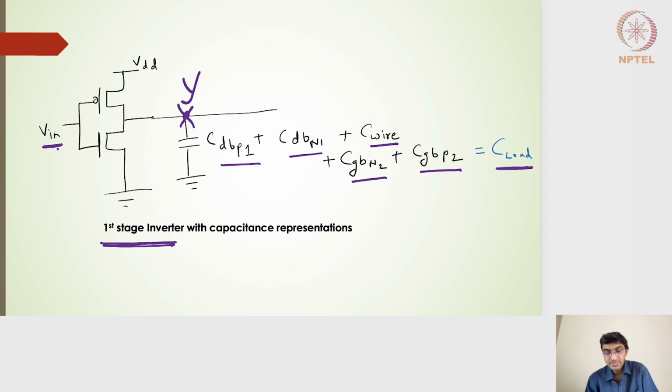So what we had seen was a completely different module on delay. We understood the definition of the propagation delay and the contamination delay, falling and then rising, and then we started looking at the inverter circuit, understood all the capacitances, the input capacitances, and the parasitic or depletion capacitances, and especially how the depletion capacitances at the output node can be made into an equivalent capacitance, because all these capacitances are in parallel.